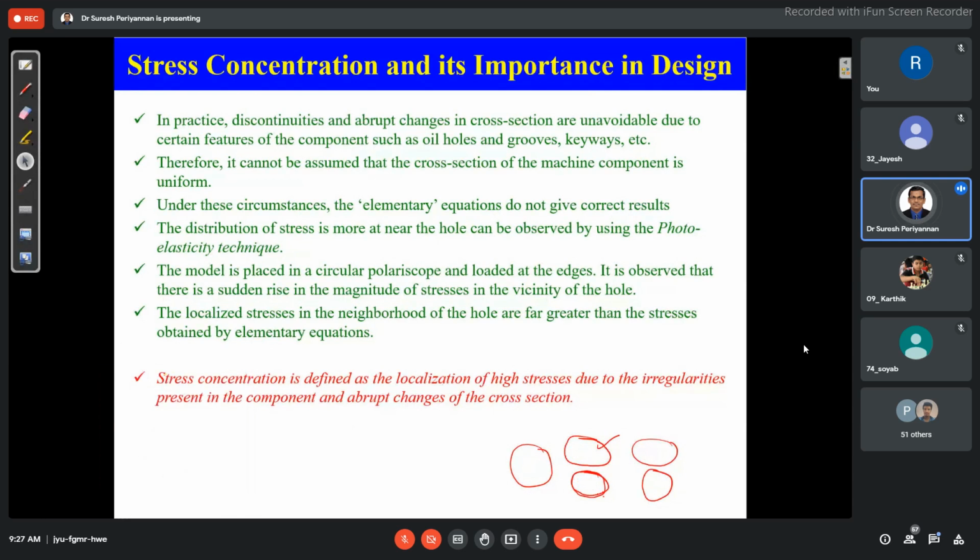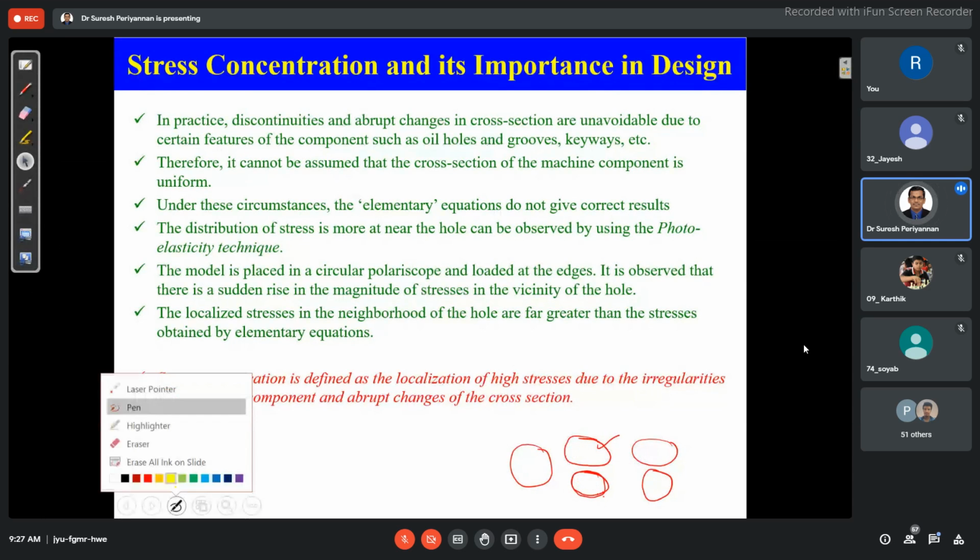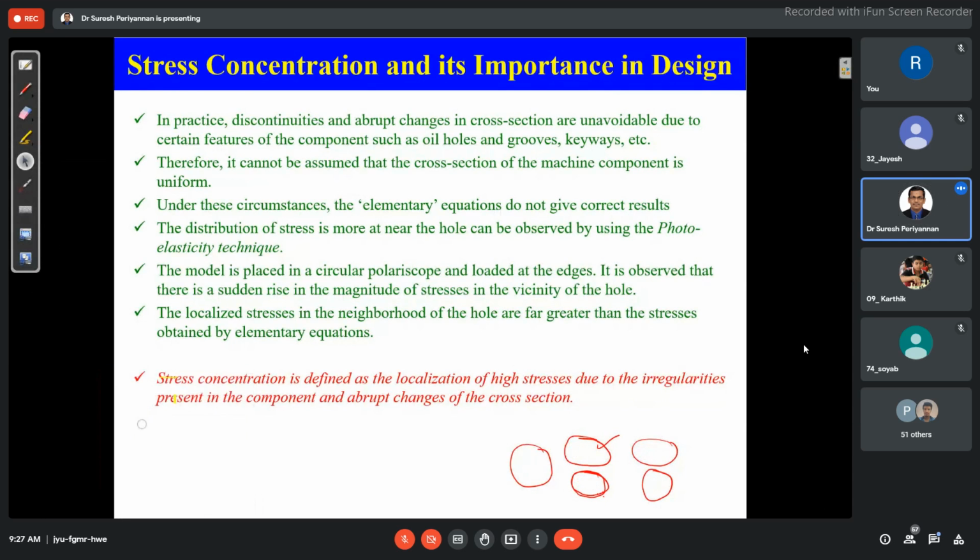You can expect this kind of question in your interview also. The stress concentration is defined as the localization of high stress due to the discontinuities or irregularities present in the component, and also when the component changes in cross section.